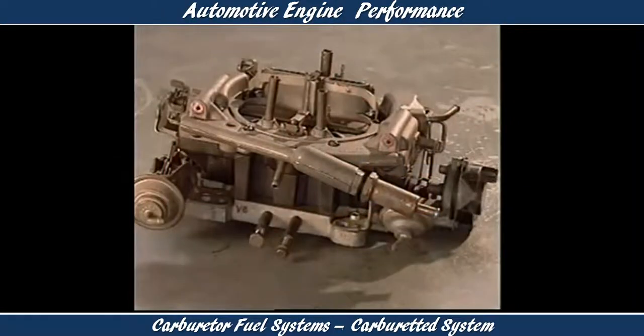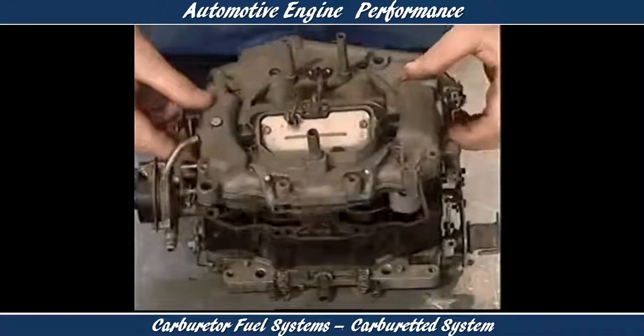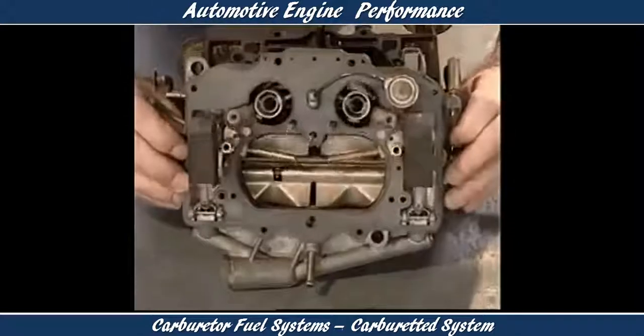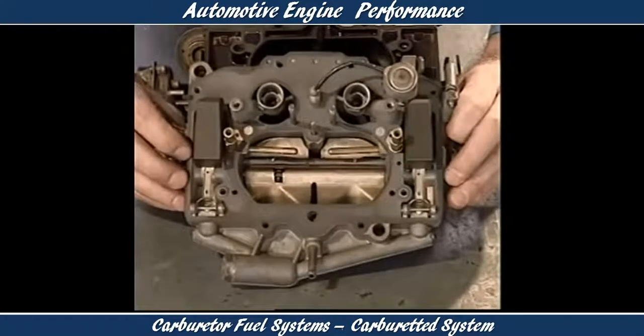Large capacity V8 engines may use a 4-barrel carburetor of two-stage design, effectively two two-stage carburetors combined, with each side supplying 4 of the 8 cylinders. A central moulded plastic fuel bowl and suspended metering system can be incorporated into the design. This gives lower fuel temperatures with more precise fuel metering and closer control over air-fuel ratios.